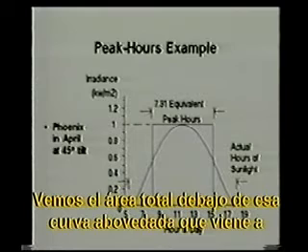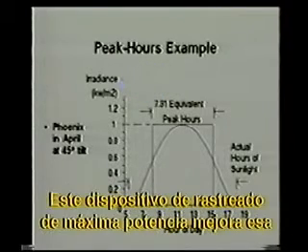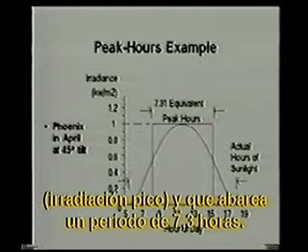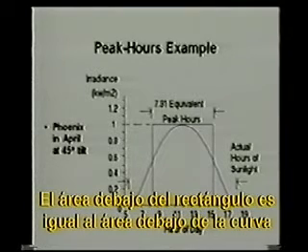We look at the total area under that dome-shaped curve. That comes to be 7.3 kilowatt hours in that particular case. We create a rectangle that has a height of 1 kilowatt per square meter, peak irradiance. And we have that rectangle span a period of 7.3 hours. The area under the rectangle is the same as the area under the sloping curve.